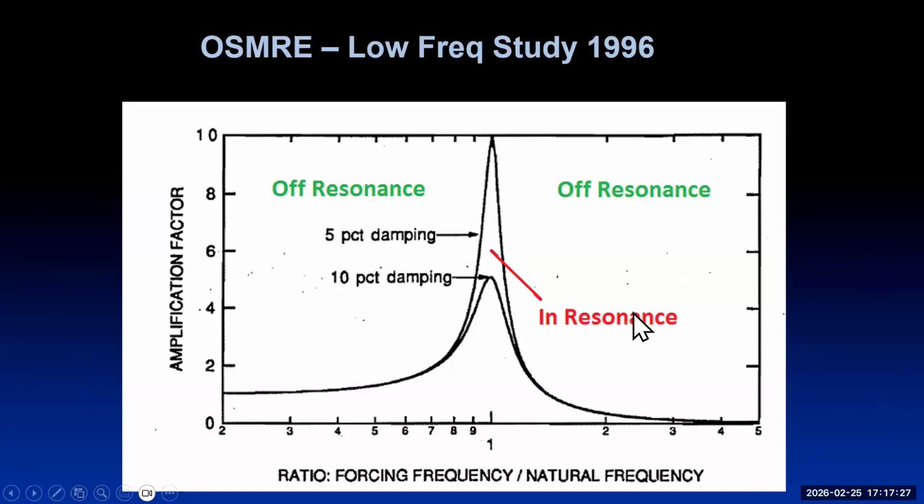And in that same study, they give this chart, which I think is a good one. It's very similar to what Alan was showing on his response spectrum, where in this case we're talking about the ratio of the forcing function with the natural frequency, where the force in the ground is aligning with that natural frequency sway, and the amplification factor when they do align. What's really important to look at is when you're off resonance, it really doesn't respond very much. It's kind of a one-to-one.